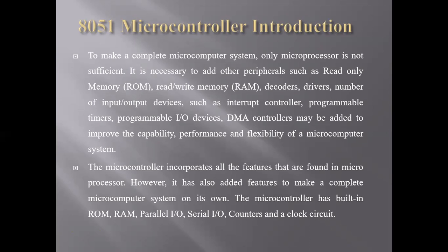It is necessary to add other peripherals such as read-only memory, that is ROM, read-write memory, that is RAM, decoders, drivers, and a number of input-output devices such as interrupt controller, programmable timers, programmable input-output devices, and DMA controllers may be added to improve the capability, performance, and flexibility of a microcomputer system.